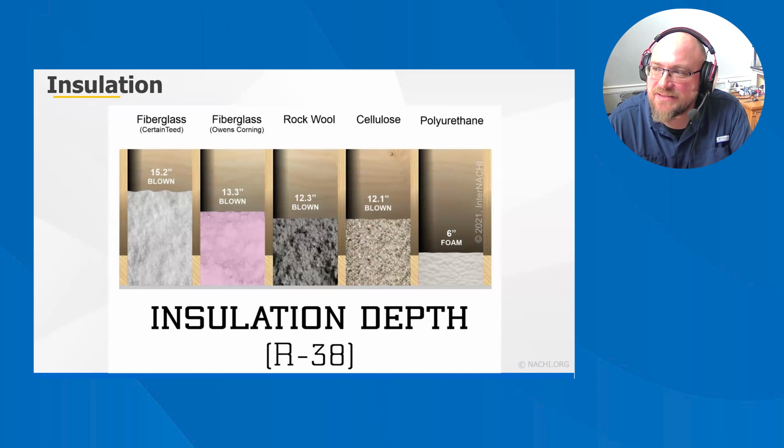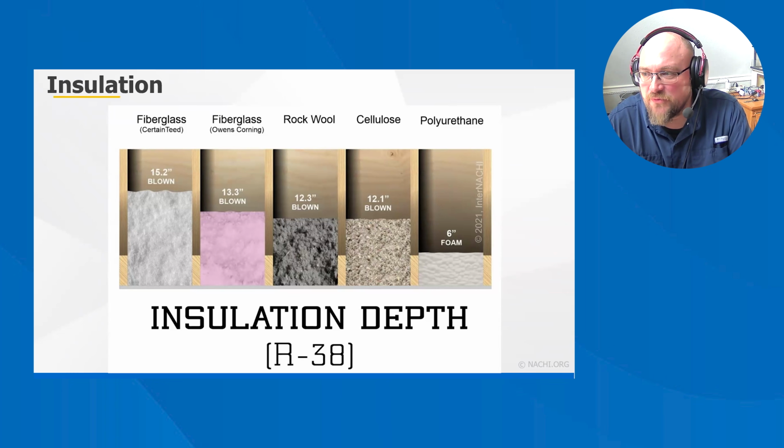Insulation in the form of batts, blankets, loose fill, and low density foams all work by limiting air movement. The still air inside the insulation is an effective insulator because it eliminates convection. Still air also has low conduction, so heat doesn't flow very well via conduction through insulation. Some foams are filled with special gases that provide additional resistance to heat flow. Reflective insulation limits heat that travels in the form of radiation. Some reflective insulation also reduces air movement, but not as much as other types of insulation.